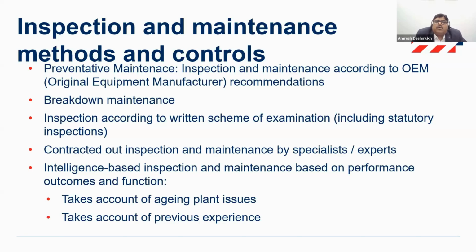Now, when you are contracting out your inspections or maintenance, which is quite often a case nowadays, ensure that it's been given to specialists or experts who are good at handling those primary equipments. And if you happen to outsource it to someone who is not known to you, you ensure that you have adequate competence validation mechanisms in place before you allow that individual to perform those tasks on your site. It has to be under your supervision, because you would be able to outsource the tasks, but you won't be able to outsource the responsibility. It still lies with you.